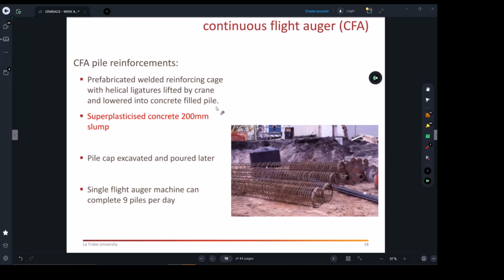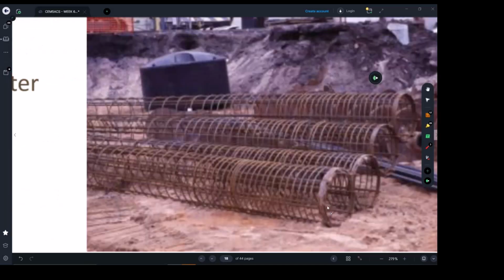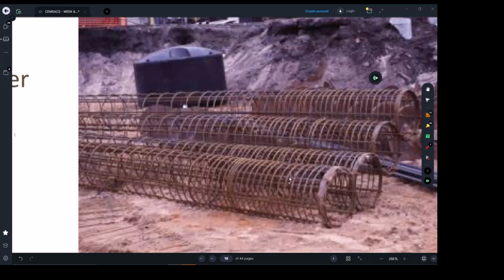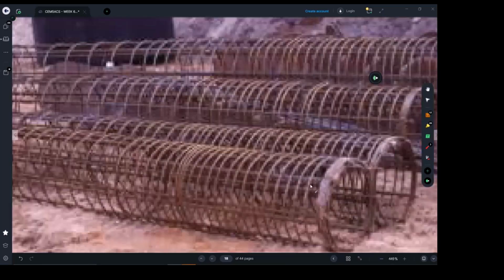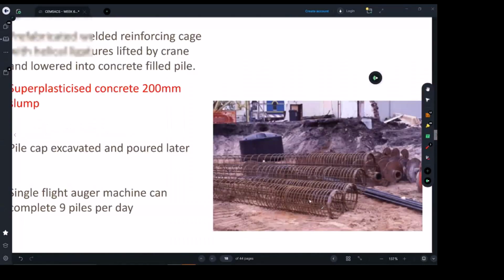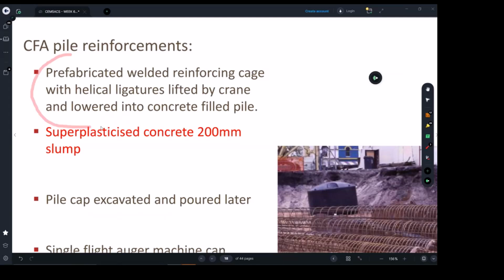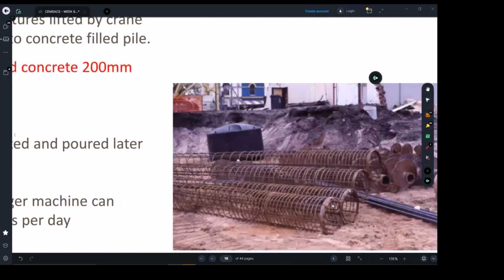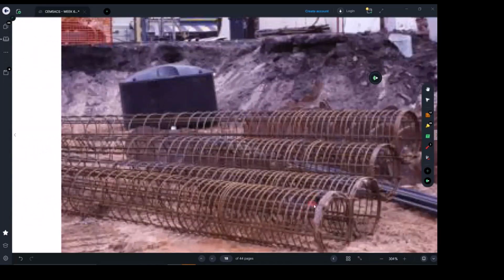Reinforcement, as we said, is going to be submerged, and one of the key things when they prepare the ligatures, as you know, in usual reinforcement exercise, you may manually tie the bars together, but with such construction arrangements, they typically are going to weld them. They're going to tack weld them. So the ligatures will typically be tack welded.